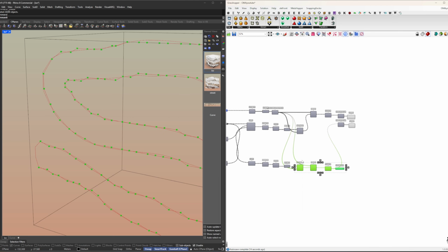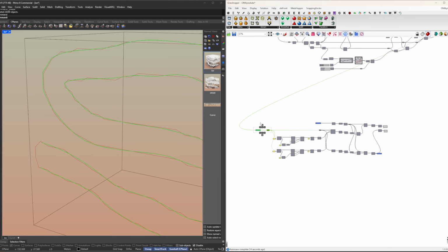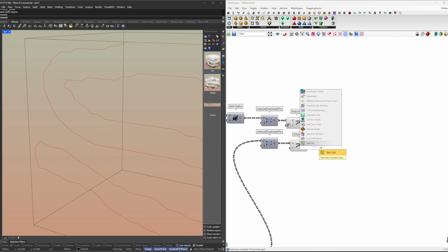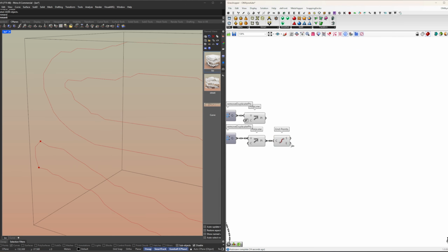Let's close this one. Let's hide also all this. Maybe this one as well. So here now I want to see the endpoints of these guys. We can actually merge them, and then we do a curve closest point. Curve closest point. Yeah, and these are my points. They can go in here. And one of them needs to be flattened, and I think it's this guy.